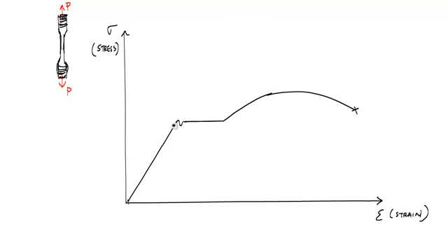Linear, it's a line. And this is called the linear elastic region, which means that it behaves in this region like a rubber band. You can load it and unload it, and it's supposed to return back to its original shape. Once we get to this point right here, this is what we call the yield point. And I've drawn here an upper and lower yield point. I think it's enough in mechanics of materials just to know that when you move out of the linear elastic region, that means you've yielded or you've become nonlinear. And this is called sigma y, the yield stress.